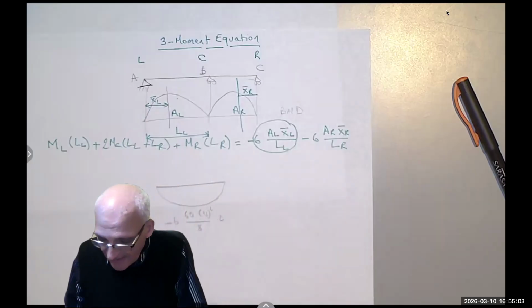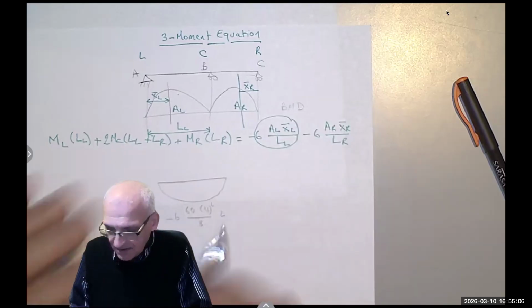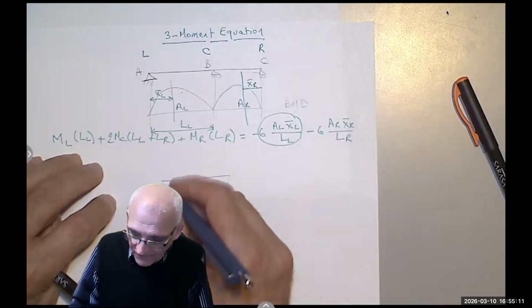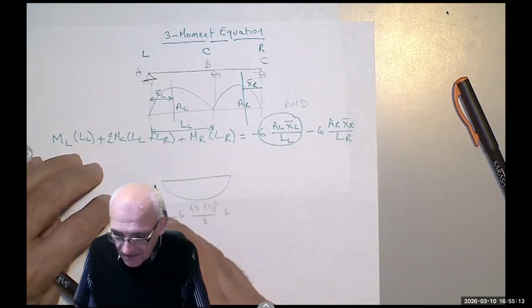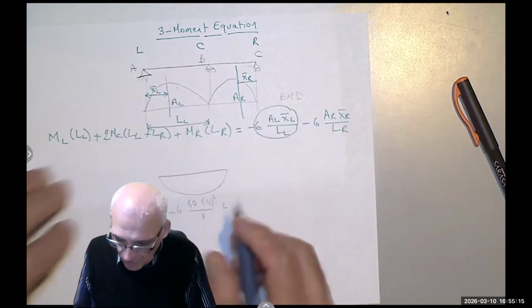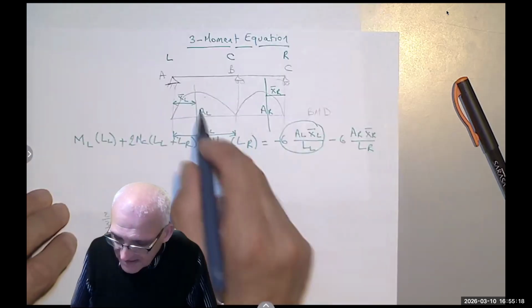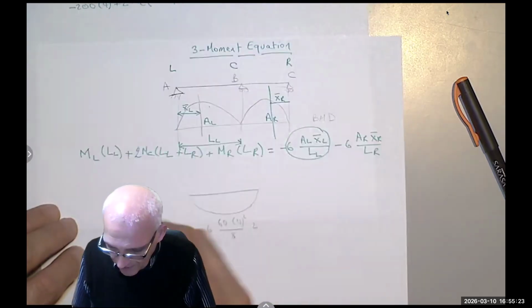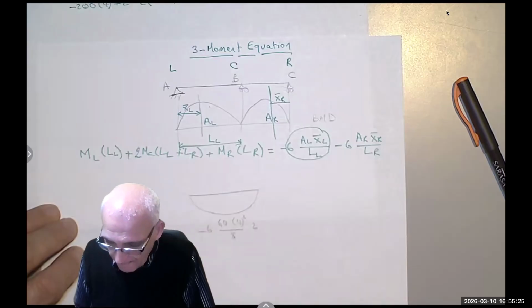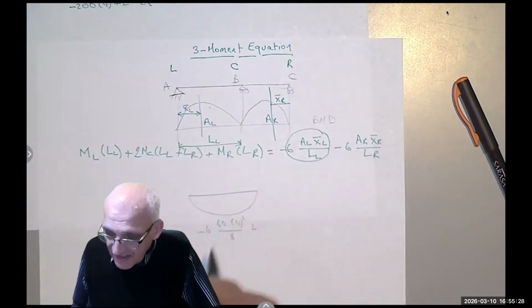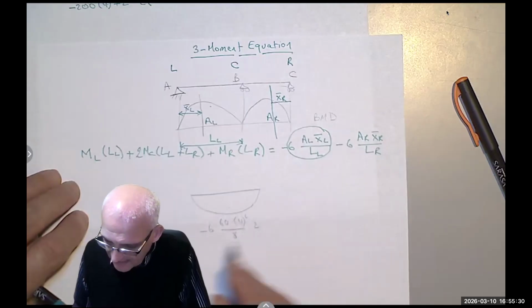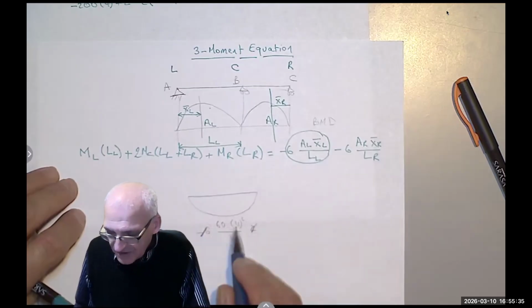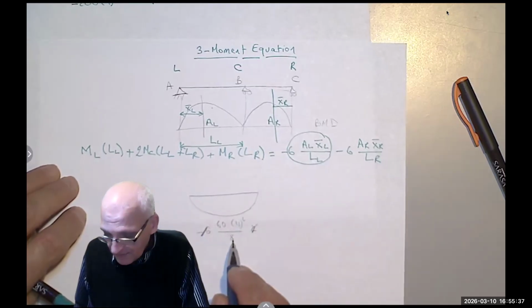Okay, and I'm sorry, this is the moment, right? But the area of the moment is 2/3 base times height. So it's 2/3 base, which in our case is 4, times the height, and the height here is the bending moment itself, which is WL square over 8, right?